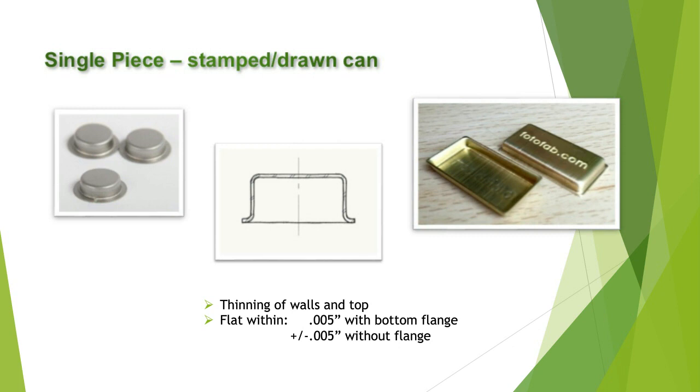But generally, tooling is going to be fairly expensive, probably somewhere in the range of $10,000 to $15,000. And the economics of that don't usually make the per piece price quantities make sense, at least not until you're looking at $250,000 to 300,000 parts a year. There are some stamping technologies that get you almost there in terms of piece part price, but you can't really go very deep on the draw.